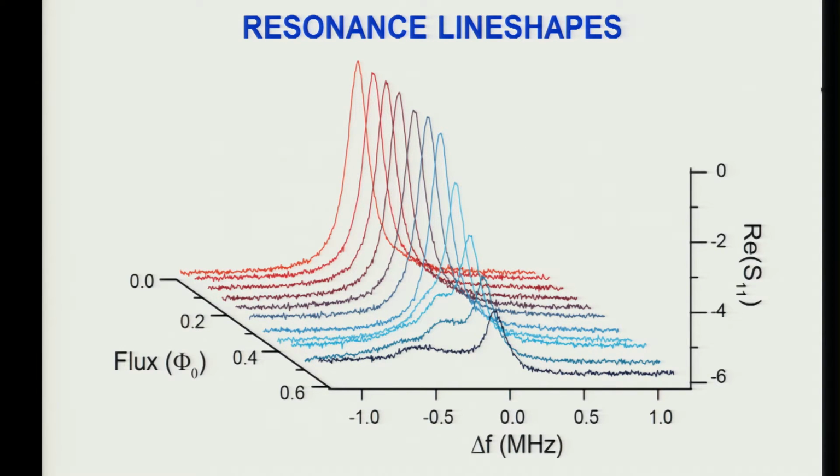This is now the microwave response at zero flux. You see a nice sharp resonance, which is there. If you now go ahead and flux tune it down, here's the normalized flux in flux quanta shown here, you develop a little shoulder, which is here. That's very strange. Absolutely deleterious to any qubit you try to make, because you just killed your line width by adding this flux. And this troubled us for at least a year.